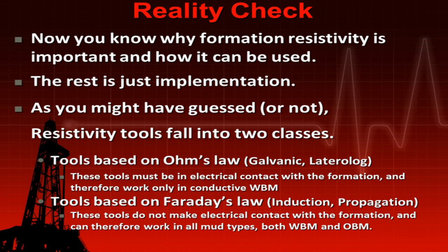And there's other tools that are based on Faraday's law, which are called the induction tools, wireline induction, or on drill pipe, propagation is the implementation of choice. So the physical principles of all of those tools are very common, and they break down into either Ohm's law, a galvanic type of tool, or an induction type of tool. And even though we call it propagation, it's still induction.